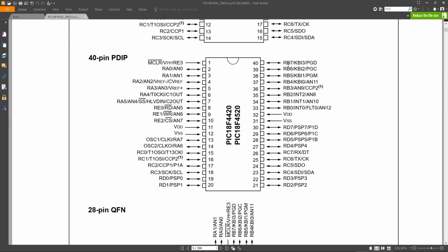Unlike someone who picks pins RB7 through to RB4, then picks RD1 and RD0 for register select and the enable. This will complicate the design, as you will see later. Why we always try to choose pins that are close to each other for a specific component is so as to lessen the constraints on the design, because you're going to find out that traces are going to conflict and they're going to intersect.